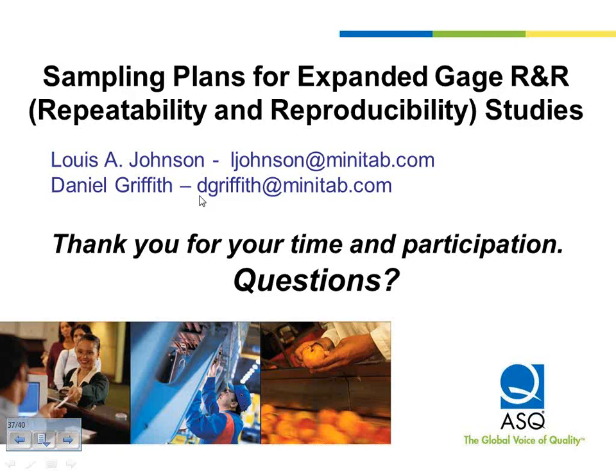Another question is: is there value in doing expanded Gage R&R between 2 different methods measuring the same feature? Oh, absolutely. Some of the clients that I worked for, one example was a client that manufactured coating materials, and they were going to measure the coating 3 different ways. They were going to measure it with an eyepiece, with a laser, and with a different drilling kind of study where they drill down to the metal, and then they estimate the slope of the line that's produced whenever they drill out the coating. So it's very, very commonly used in comparing 3 different test methods.